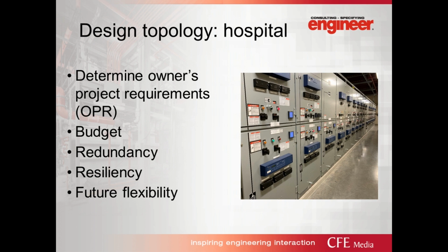It provides explanation of the ideas, the concepts, and the criteria that are considered to be very important to the owner. This OPR is typically developed by the owner, but sometimes it's developed together with the design engineer, working through all of the options to consider. So decisions are typically made in a hospital with respect to budget, the desired level of redundancy, the desired level of resiliency, as well as future flexibility and scalability. Defining the future growth for facilities or campuses could have drastic impact on the emergency power system design. So it's important to have a good understanding of the client's overall goals when initially working through the design topology.